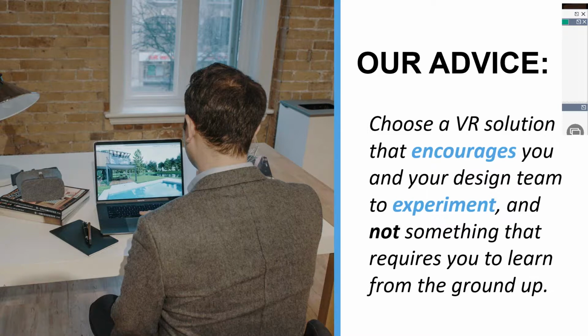If you install the plugin that matches the CAD program in your workflow, you can make any 3D CAD design into a VR design. Click on the Yulio plugin button in your CAD program, and once the project is done rendering, you can upload the cube map file to Yulio, and there you go. A virtual reality experience you can share with your client.